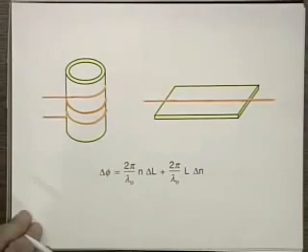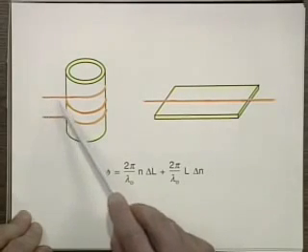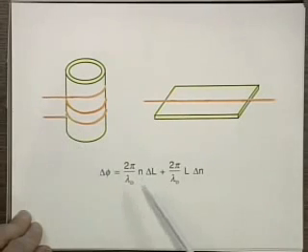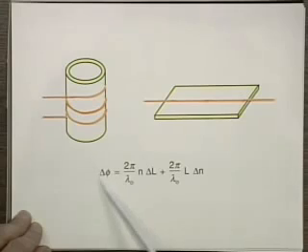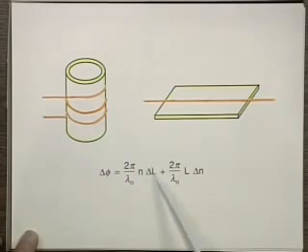And now I wanted to just say again a few words about phase modulators. Now, phase modulators, how do you do that? How do you modulate the phase of the light propagating in the fiber? Well, again, there are many ways, because if we stretch the fiber, if we do something to the fiber, we can change essentially the index in the fiber, or change the physical length of the fiber, and then we get a change in phase, delta phi, that's proportional to either the change in the length of the fiber or the change in the index of the fiber.